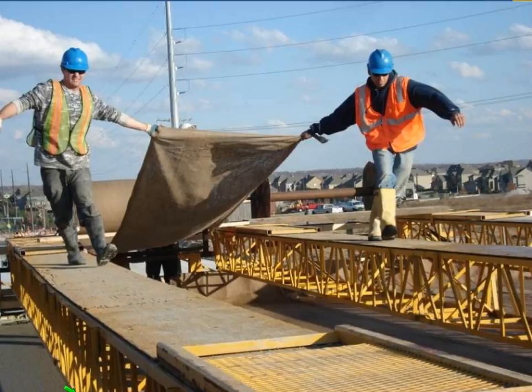Here's an example, very efficient, very low-cost way to do it. This is all pre-saturated, fully saturated. You never want to put dry burlap down on wet concrete. Don't expect the bleed water to get you the curing. It's a three-person crew. You can see there's one down here, there's legs, the other two guys hauling it across. Very efficient. It's all pre-cut. They can cover this concrete up in under 10 minutes. They can put the second layer down within another 5 minutes, and they get extremely good results as far as curing. Plastic shrinkage cracking doesn't exist on bridge decks that are constructed this way.